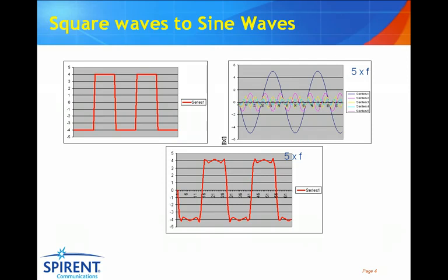On the left, we've got a square wave, which has basically been sampled by 5 different frequencies shown on the right. Underneath, you can see the representation of that square wave when we add the frequencies together. That is, wherever the frequencies intersect, we add the values together and we reproduce an approximation of the square wave. By adding more information to the graph, we can actually sharpen up the square wave. To do that, we would have to add more and more frequencies.